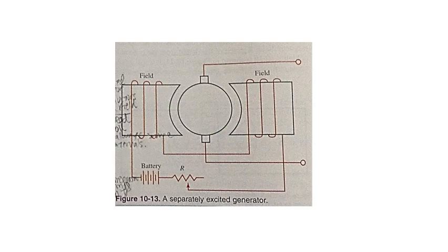Separately excited field generator. The generator output is determined by the strength of the magnetic field and the speed of the rotation. The field strength is measured in ampere turns. So an increase in current in the field windings will increase the field strength. Output voltage is in direct proportion to the field strength times the speed of rotation. Therefore, most output regulating devices depend on varying the current in the field.